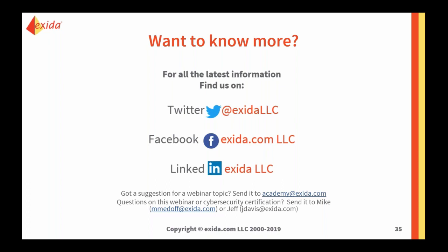It doesn't get into the level of detail of 62443 that defines more details about what needs to be included in the threat model. So in 61508, it just defines at a very high level that yes, you do need to do some sort of threat analysis and determine if security threats are something that you need to be concerned with, that could lead to dangerous failures. And then if so, you must include those in your risk analysis and put in steps to mitigate those threats. So that was also a very good question.